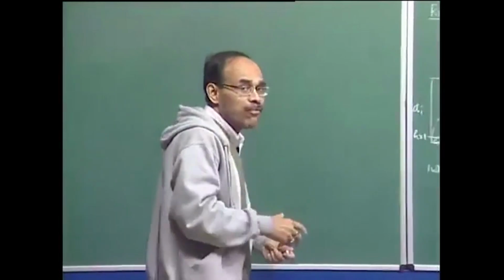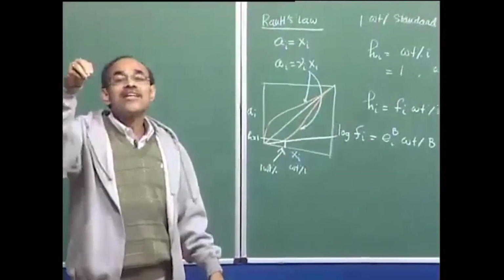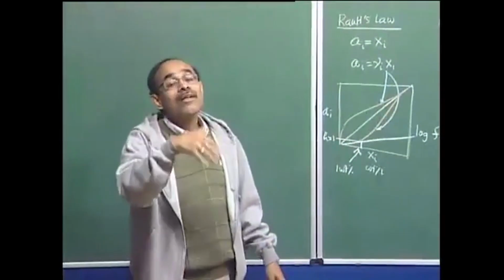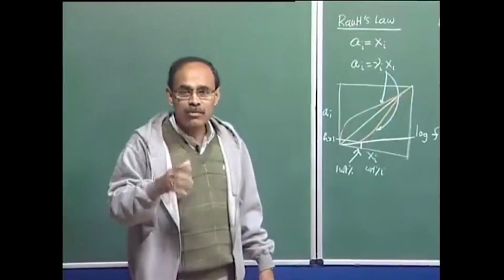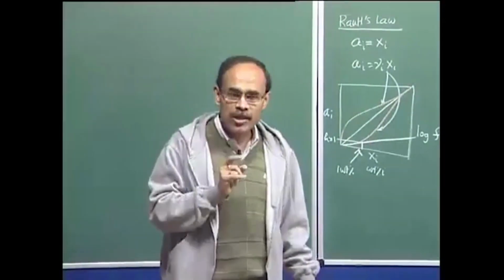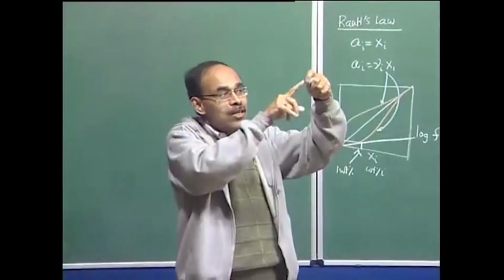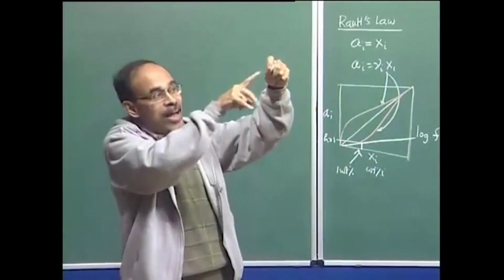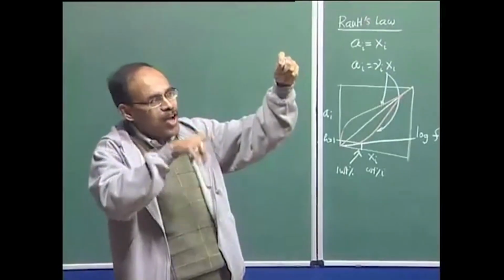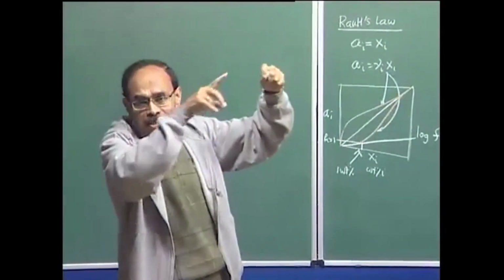So, we understand that the introduction of a third element will either increase or decrease the activity of the second element, and therefore all the solutes present in a steel melt will influence the activity of a given species. For example, the activity of oxygen will depend on the activity of sulfur, on phosphorus, how much silicon is there, how much manganese is there.